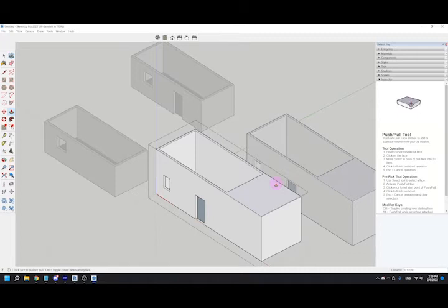That can be very handy with these small features that you have inside of a design. So for instance, if I designed a kitchen table with a chair sitting around it, and I had 6 of that same chair all sitting around the table. If I then wanted to make changes to one of the chairs, if they were components, I could just change that one chair and all 6 of those chairs would update automatically. So that way I wouldn't have to go make that same change 6 times.